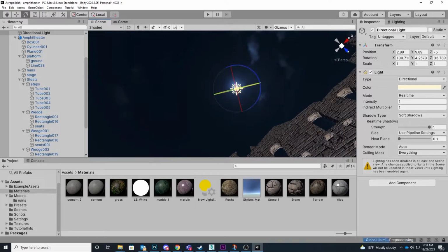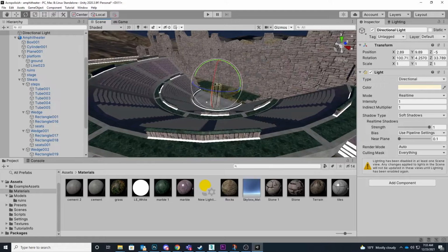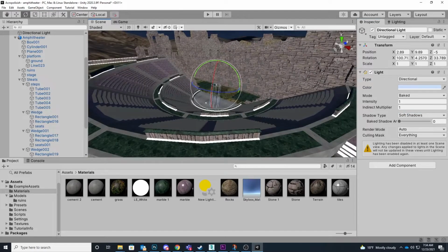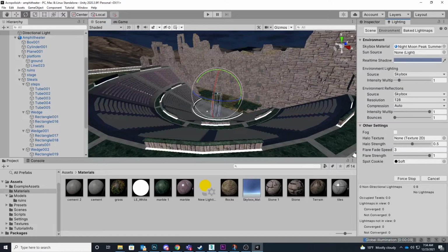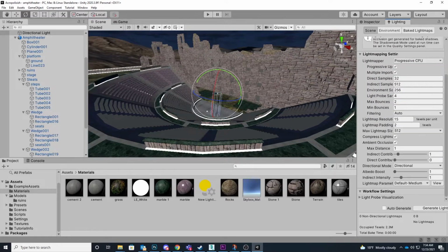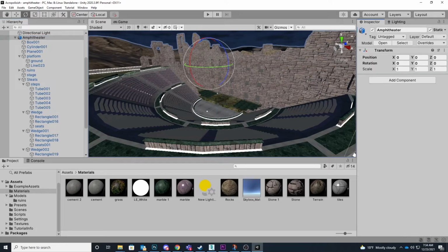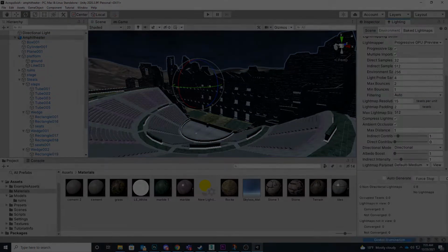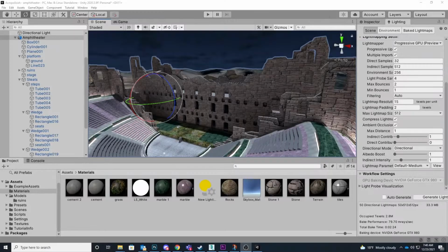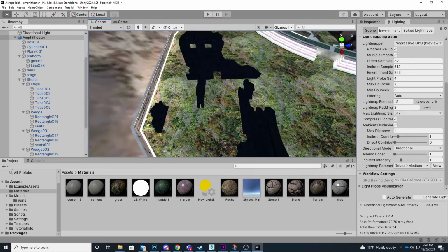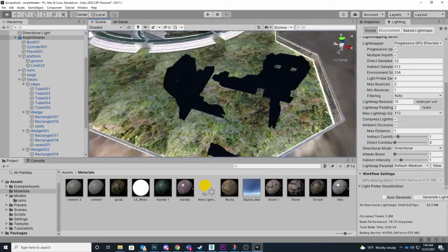Setting up the direct light. A little trick I do is if there's a point of light in the skybox that's going to be the source of light for the direct light, I'll position the direct light between myself and that point in the skybox, and then rotate the light so that it's pointing directly back at me, and that'll make the lighting match up very naturally with the skybox.